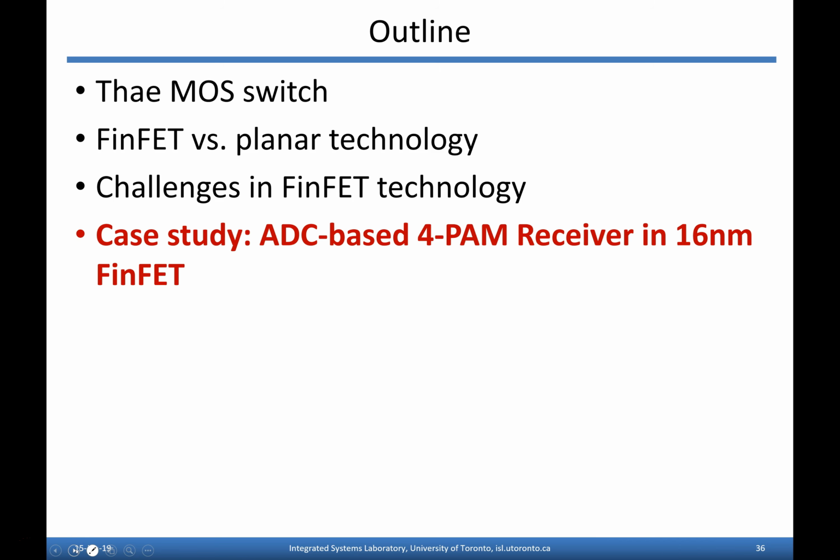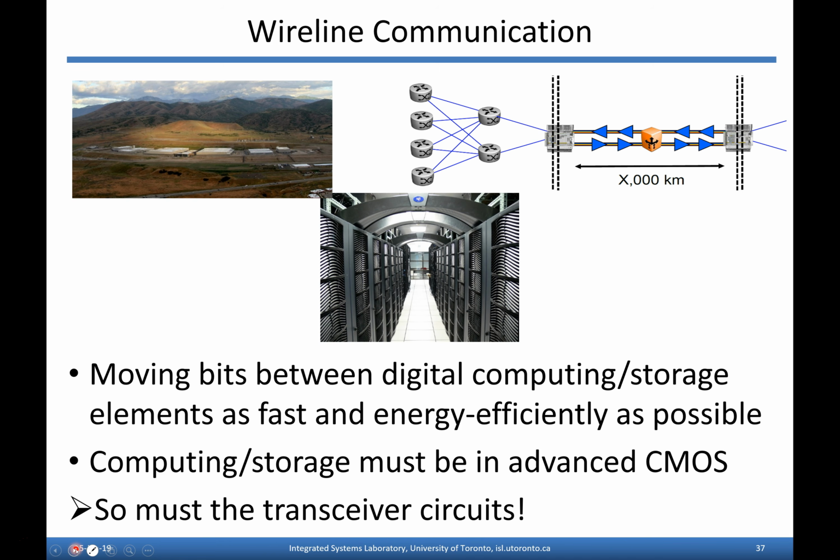So just a couple of slides here showing an example of a FinFET design from our lab, because with all these headaches and all these challenges, you might say, well, why even bother doing this, right? Well, in this case, this project was interested in wireline communication that takes place within some of these huge data centers. Obviously, in a data center, it's very important to move bits very quickly, but the circuits that are doing that job have to be integrated onto the same chips that have a lot of memory and a lot of computation on them.